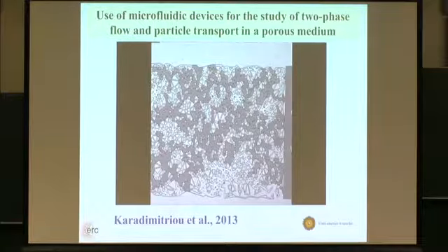The interface can be stuck because of capillary forces, because the interface cannot go into small pores. As I said, this solid has preference for the wetting phase. And the smaller the pore is, the more difficult it is for the non-wetting phase to go into that pore, because it has relatively more solid area compared to the volume of the pore. The capillary force is larger, so it cannot go in there unless you increase the forces. So the interesting thing is that these interfaces play a significant role in whether this process would occur or not.